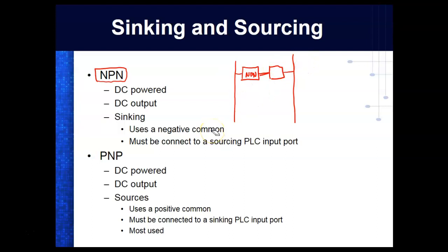Now these are DC sensors. If we got AC inputs, it makes no difference. If we got a push button, push buttons don't care. Electronics care where you put your negative and your positive. If you don't believe that, go out there and swap the battery cables on your car. You're going to burn up a lot of stuff, right? A whole bunch of fuses. So electronics are sensitive to the polarity that you apply to them.